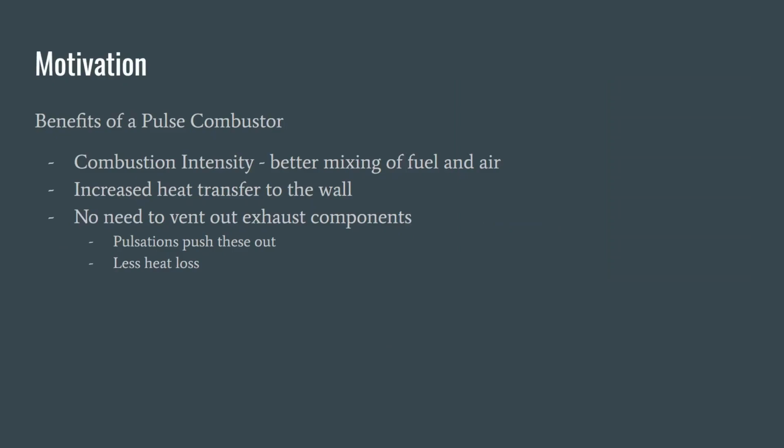So why do we even care? Pulse combustors actually have some benefits over normal combustors. You have better mixing of fuel and air, leading to more intense combustion. You are able to transfer much more heat through the walls, as the otherwise present insulating layer of the tube is stripped away by the acoustic velocity. And finally, the pulsations of the combustor will push out any exhaust components that in a normal combustor would have to be dealt with in some other way, making pulse combustors much more simple and privy to reduced heat loss.